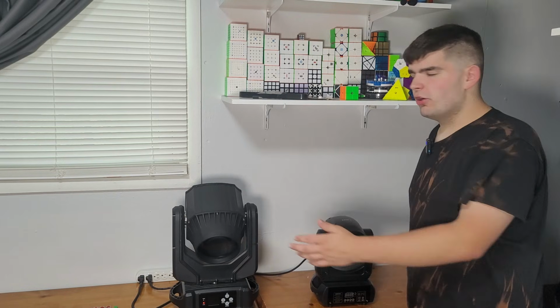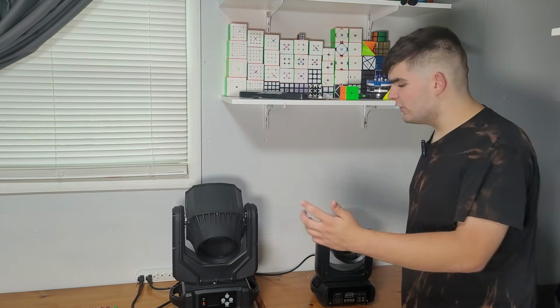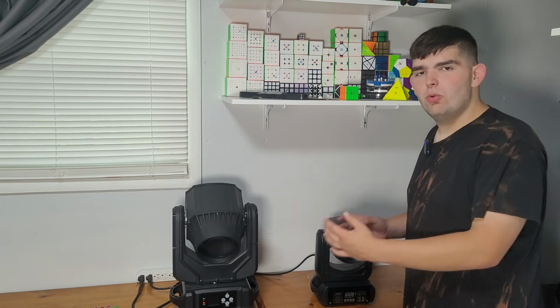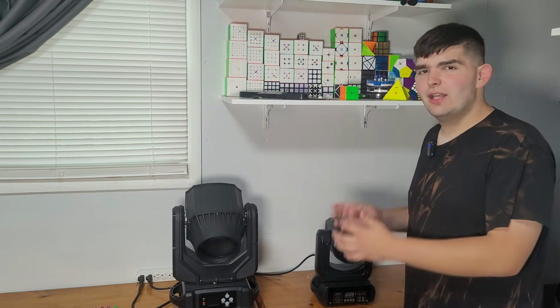And the first fixture could start at 1 again, and then the next fixtures would have to start on the next open channel. But that's how you hook up anything DMX to each other, and that's how you set the DMX address.